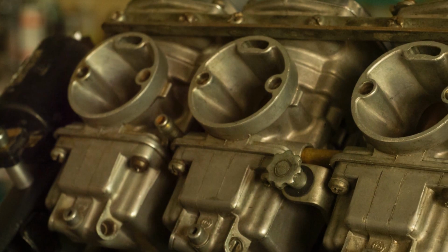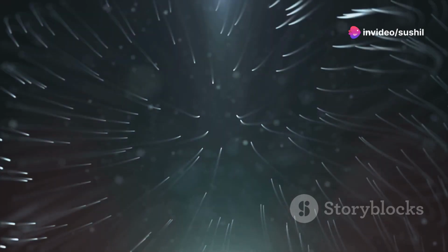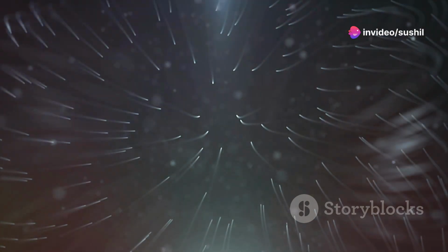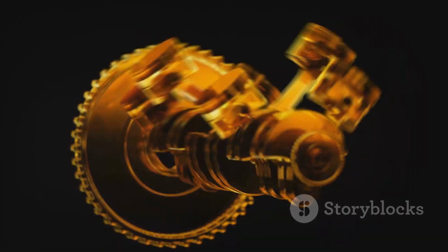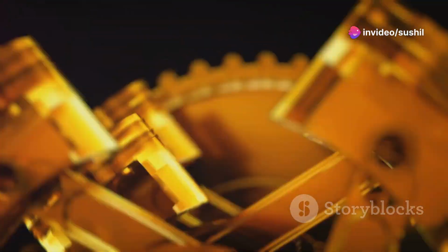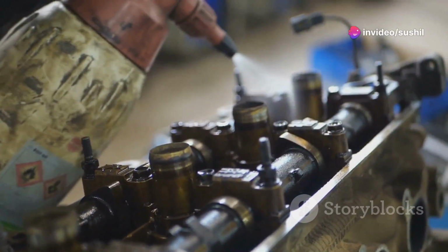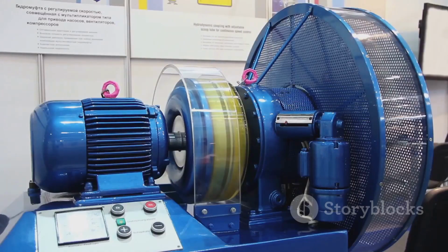As air flows through the carburetor, it encounters this narrowed venturi section. In accordance with Bernoulli's theorem, the air speeds up as it squeezes through this constriction, causing a drop in pressure. This low-pressure region within the venturi acts as a vacuum, drawing fuel from a reservoir and mixing it with the fast-flowing air. The fuel-air mixture is then delivered to the engine cylinders for combustion. The venturi effect, a direct consequence of Bernoulli's theorem, finds applications in a wide range of devices beyond carburetors.